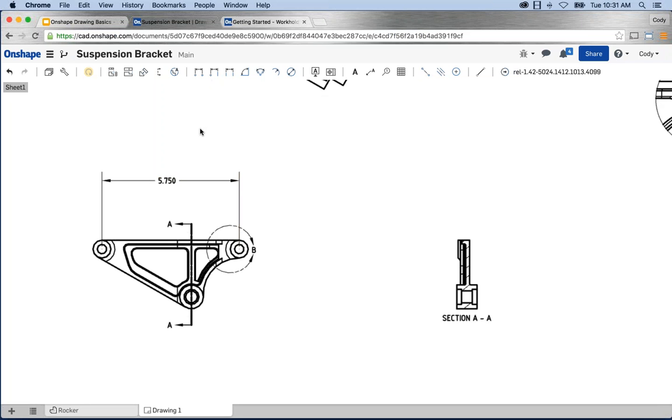Now, a number of different dimension types. 2-point linear dimension accomplishes many different dimensions, so you can do quite a bit with it. There will be certain limitations. So one example I like to point out is, let's say, for example, I wanted a dimension from the center point of this circle parallel to this edge. So I want the distance, the orientation from this point to this horizontal edge out. If I try and do a 2-point linear dimension, and I select the circle, and I select maybe the midpoint of this edge, I do not get a dimension that's parallel with that edge, right? Because it's between 2 points. So this is an example where the point line dimension becomes very useful, right? I select point line, and now I get a dimension that's parallel with that line.